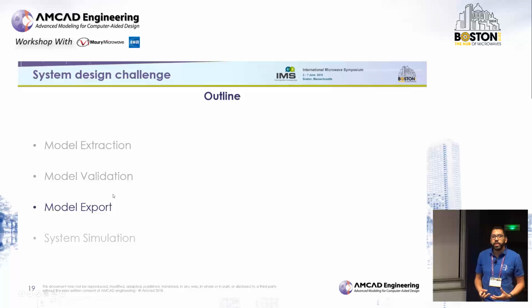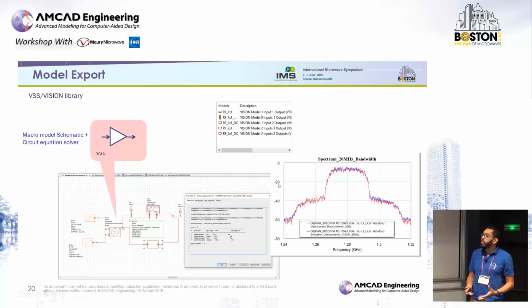Once the model is validated and qualified, it can be exported to a third-party simulator such as VSS. Model export is more than just an export. The export feature allows you to export a simple circuit model or a subsystem macro model if multiple circuits have been concatenated together.